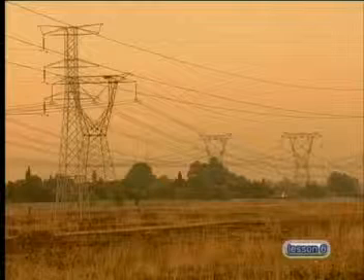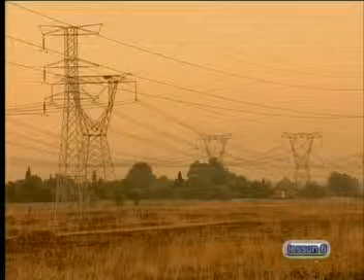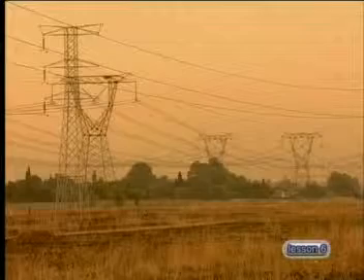What happens? The moment you step the voltage up, the current flow drops. If the current flow drops, we reduce the potential for generating heat. We can use a thin conductor made of copper and aluminium that can conduct electricity efficiently and effectively over vast distances. With a lower voltage, higher current, you have to use a robust conductor. So we cannot afford to use that to transmit electricity over vast distances. So from this power transmission network, the electricity is distributed over the length and breadth of South Africa.